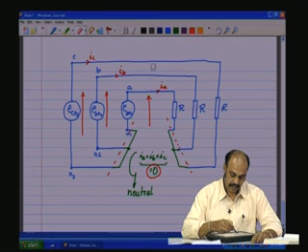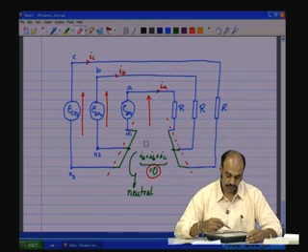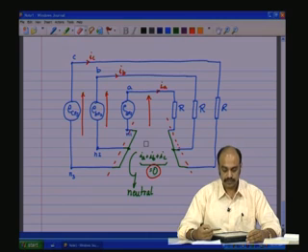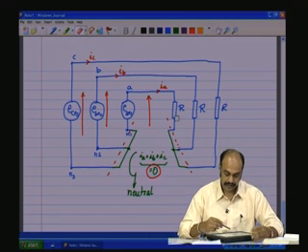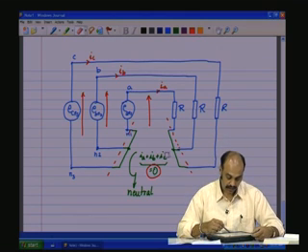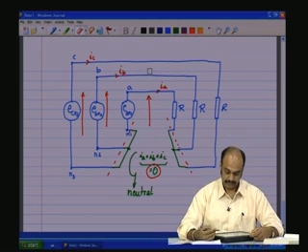You see, a 6 wire system became a 4 wire system, and from the 4 wire system, because of the applied constraints and loads being balanced and equal, you have IA plus IB plus IC is equal to 0 at every instant of time. So, it is equivalent to having no wire here, and you can just make it into a simple 3 wire system.